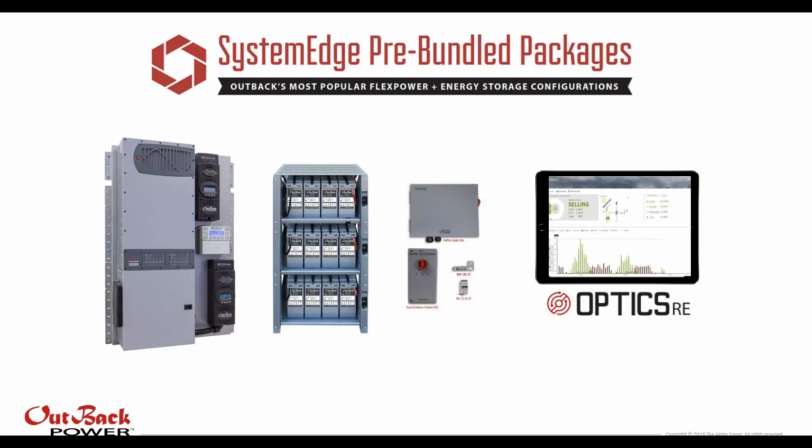Each SystemEdge package includes one of our FlexPower pre-wired power systems. You'll see on the slide there, we've got our FlexPower Radian system, which includes an 8 kilowatt Radian inverter with its load center, a pair of FM80 charge controllers, and a MATE system controller. All of that's pre-wired, so basically, you just need to connect the battery to it and the loads to it, and essentially, it's just the external connections you need to make there.